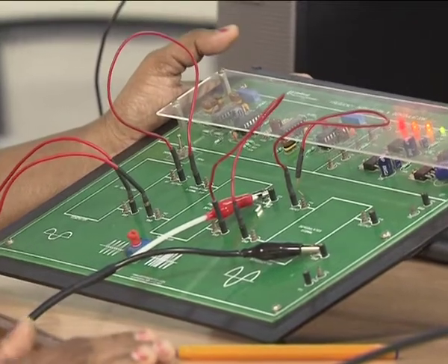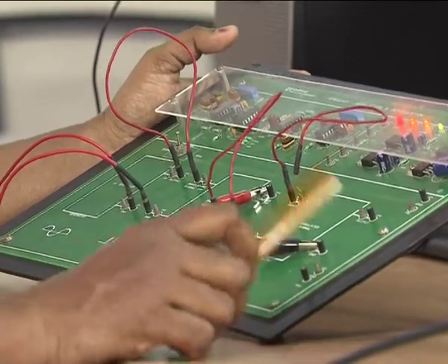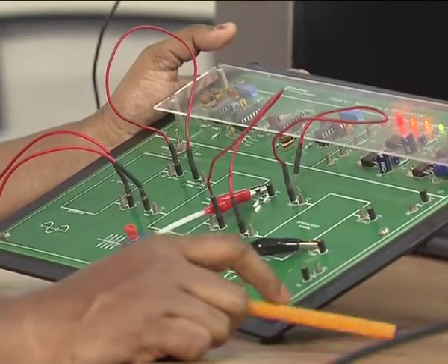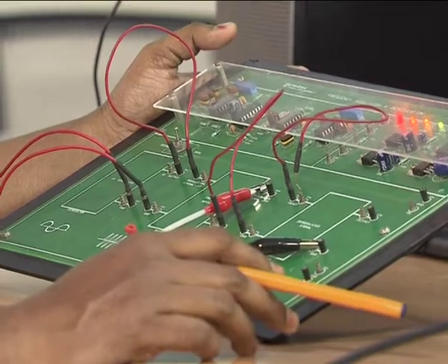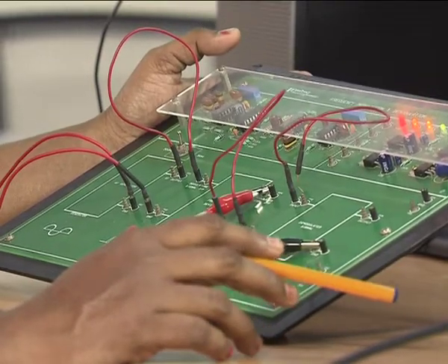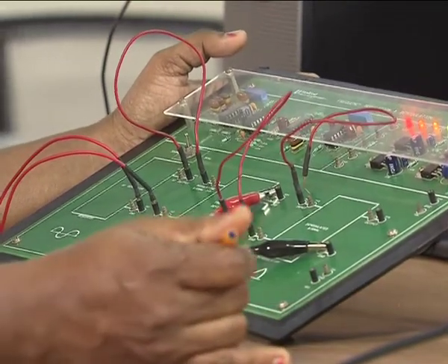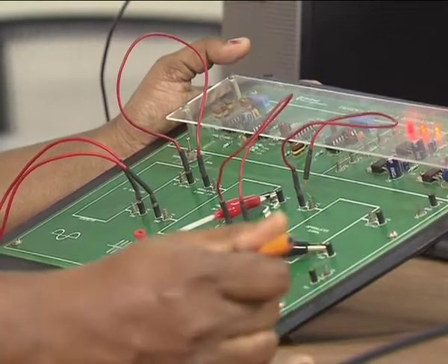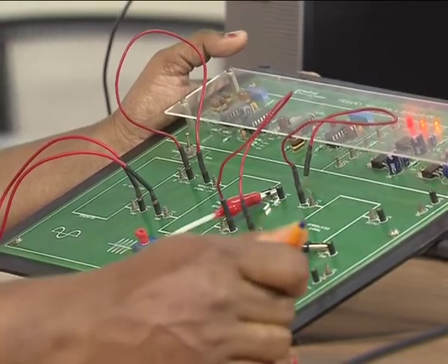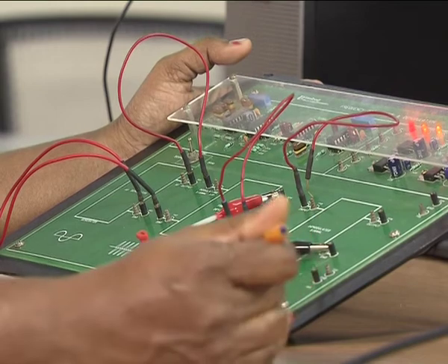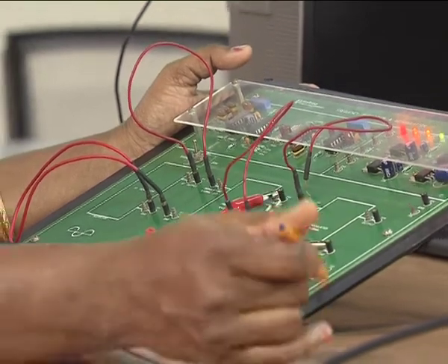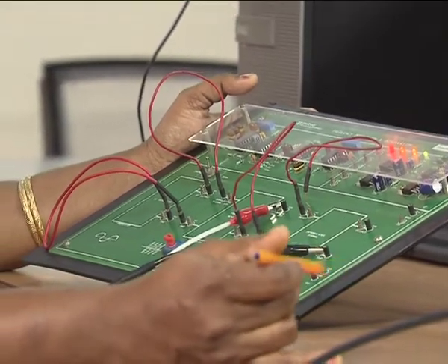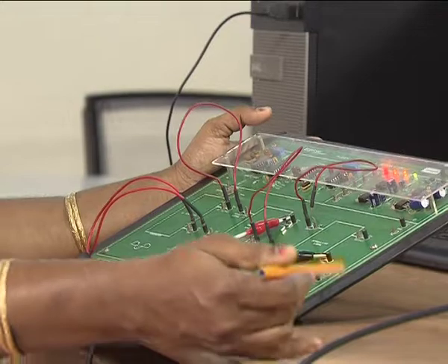To demodulate an FM, we will be using a PLL, called a phase lock loop. The PLL creates errors with respect to the difference in phase between the input signal and the VCO output signal. If the frequency is different, an error signal equivalent to that frequency difference will be produced. This error voltage is taken as the output.